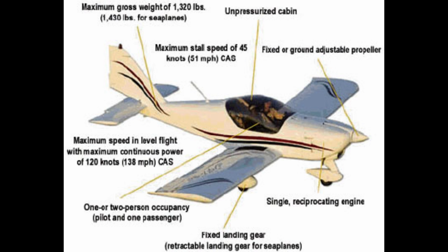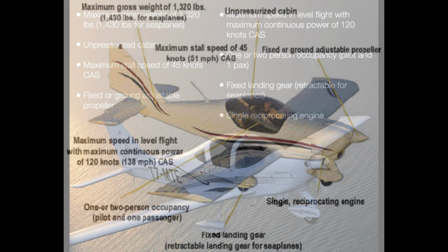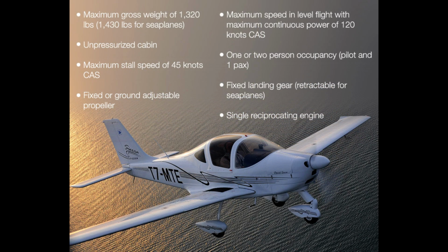When the aircraft is complete, with the airframe, engine, and propeller, it is inspected and the FAA issues an airworthiness certificate for the aircraft. Having an airworthiness certificate means the complete aircraft meets the design and manufacturing standards, and is in a condition for safe flight. This airworthiness certificate must be carried in the aircraft during all flight operations. The airworthiness certificate remains valid as long as the required maintenance and inspections are kept up to date for the aircraft.